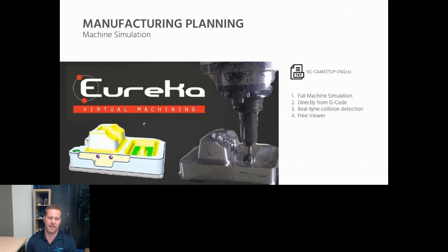So what it'll do is it'll take that G code, you can do the post-processing on it and then simulate it how it would with the actual controller on the machine. It's reading through that G code versus the simulator in CamWorks or SolidWorks CAM is just going through the different operations and toolpaths that you've defined. But there can be some translation, or there will be some translation from that original NC export to whatever language or version of that code that the controller needs.